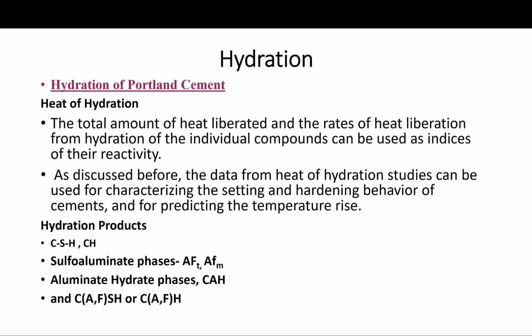Okay, the total amount of heat liberated and the rates of the heat liberation from hydration of the individual compounds can be used as indices of their reactivity. And we touched upon this before. I discussed before that the data from the heat of hydration studies can be used for characterizing the setting and hardening behavior of the cements, and also for predicting the temperature rise.